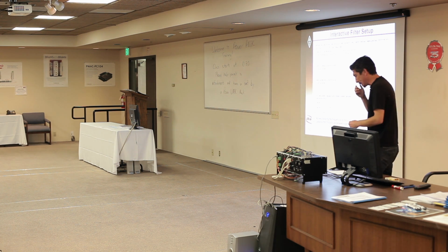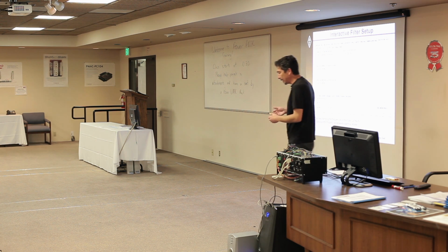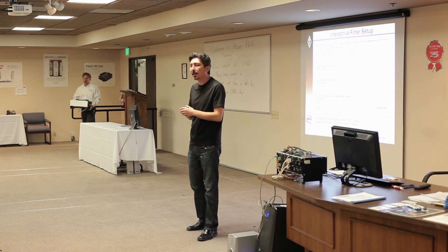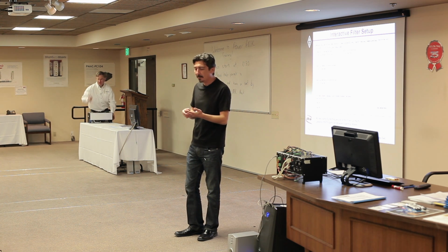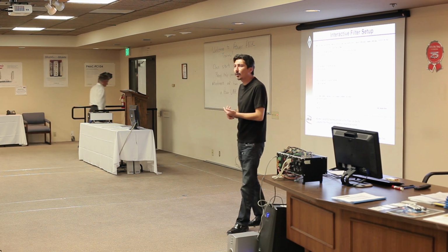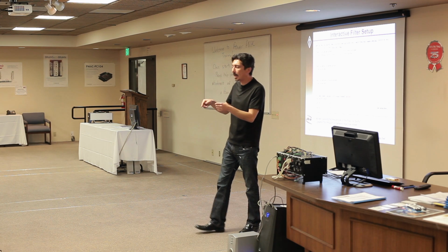And the last thing that is not here, but is going to be there, is what we call iterative control. Hopefully in the next release; right now it's actually being implemented for CAM tables, and it's called CAM iterative control. The idea behind it is actually quite simple. If you've heard about iterative learning control, as soon as you have a cyclic motion, such as a CAM, it repeats itself. And there are always disturbances that you don't know much about. But if I'm going through each cycle over and over again,